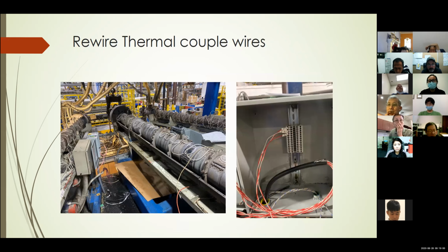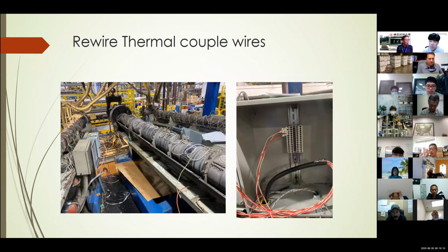What our plant does is plastic processing. Melting the raw material is necessary. To melt resin, it must have a lot of heaters to create heat. To control the heater temperature, a thermocouple must be installed in the barrel to measure the actual reading and compare it to the setting for heating control. Thermocouple wires sense temperature change through different metal materials with different impedance and characteristics.